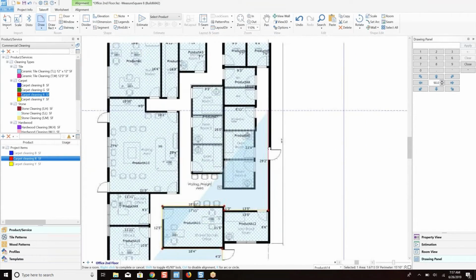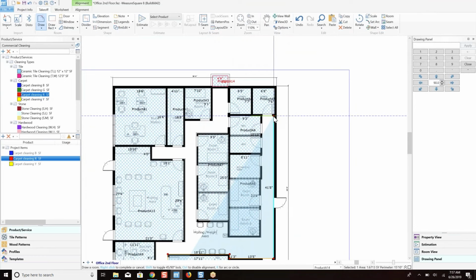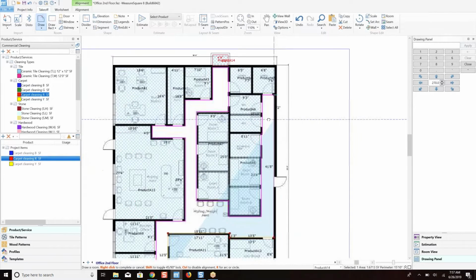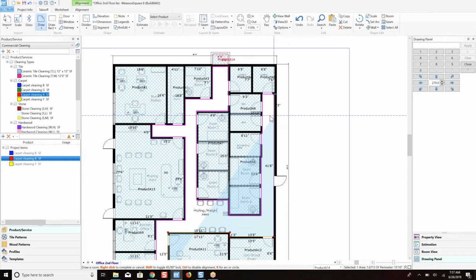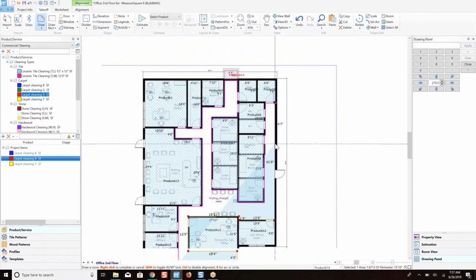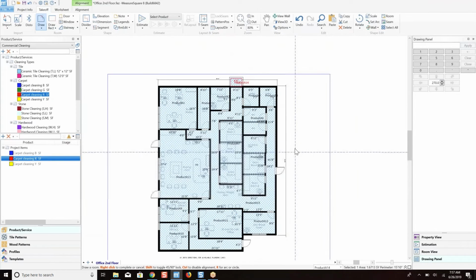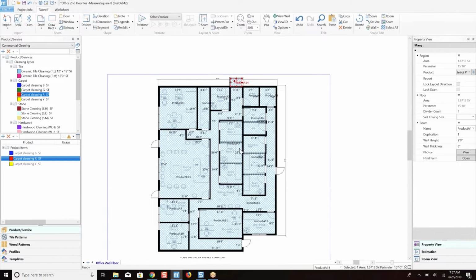And now if I did this correctly, when I get back up here, we'll see a purple line, which we do. So that purple line sees a complete path. It's like completing a circuit. And because I drew this one up here, it can go right through here and not stop. If I didn't draw that, I'd have to keep on tracing. So now when I right click, I have the whole hallway and I'm done tracing the rooms.